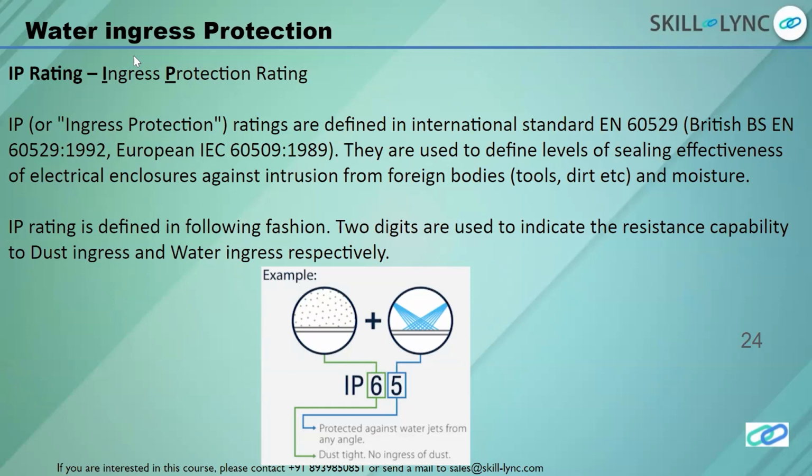Sometimes you can see IPX7 or IPX6 mentioned. The X generally means that there is no dust protection available, only water protection. This can be seen for gadgets in your households. IP69 is what we generally see for automotive applications, which is the highest standard. In automotive applications, we use it for a long term, and your vehicles go into different areas and water conditions, with wires laid down throughout the vehicle.